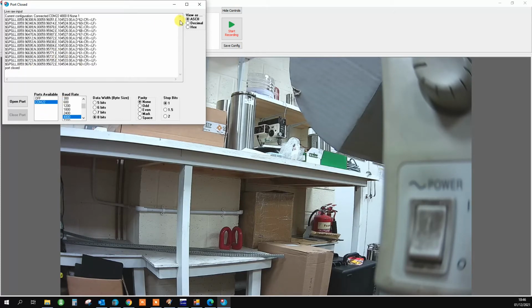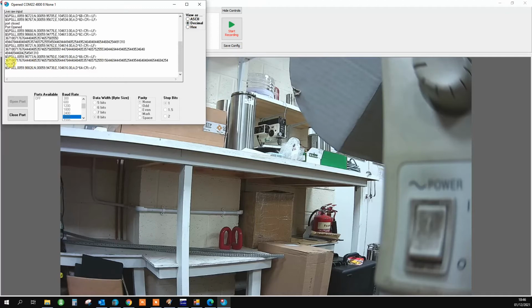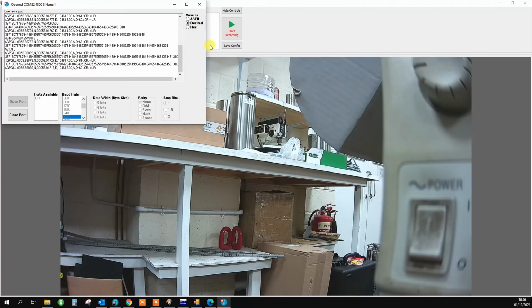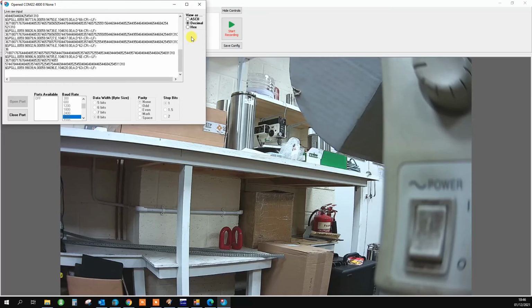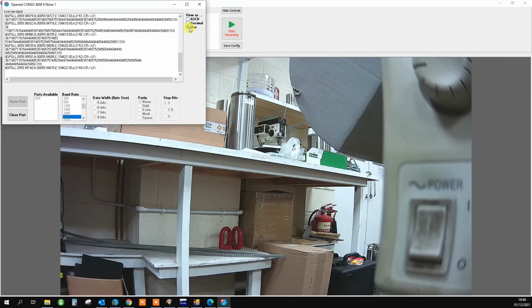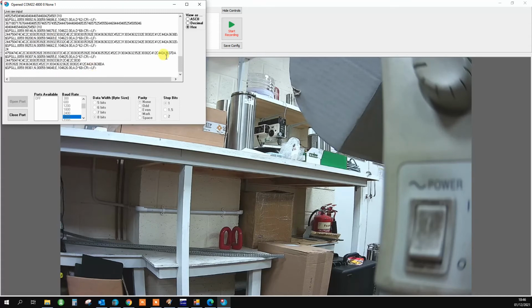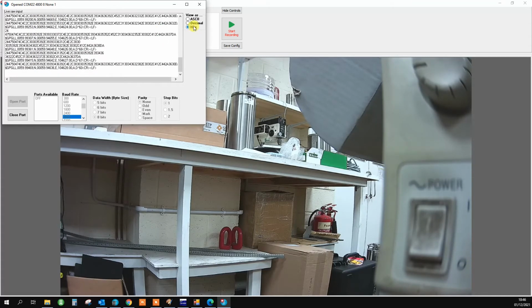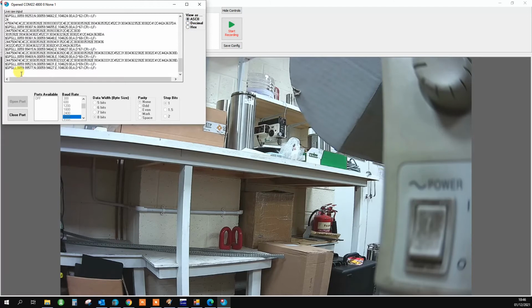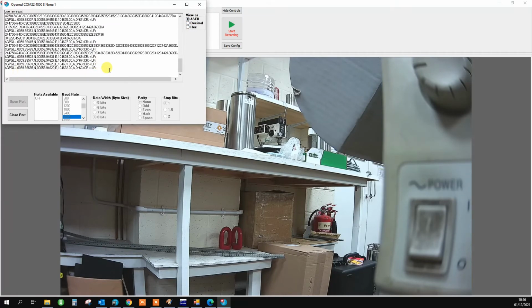So you can view the received data in a variety of formats to help debugging. I've opened the port up again and clicked on decimal. You can see a decimal representation of the binary data, or a hexadecimal representation. But for our purposes, mostly you would just click on ASCII. That then just gives you the raw format.